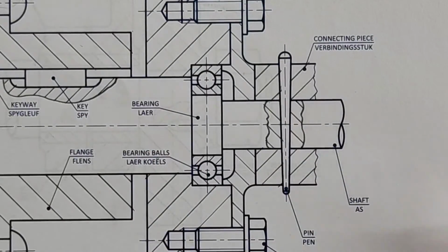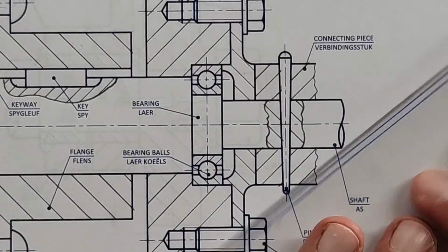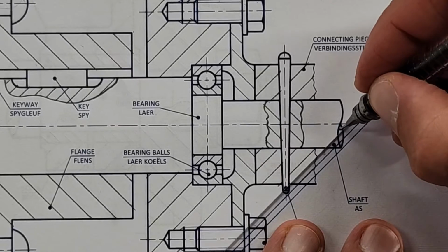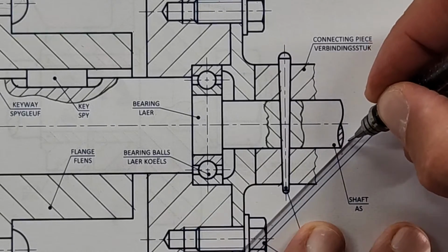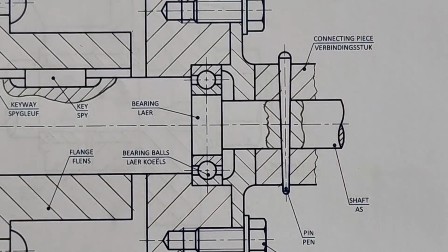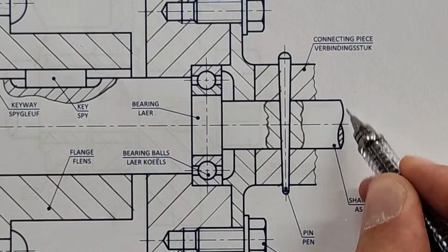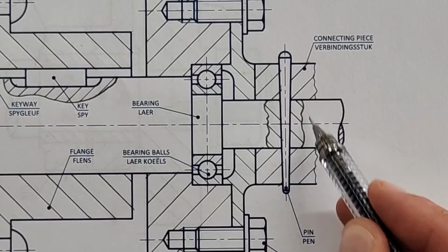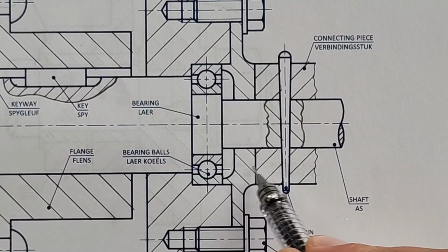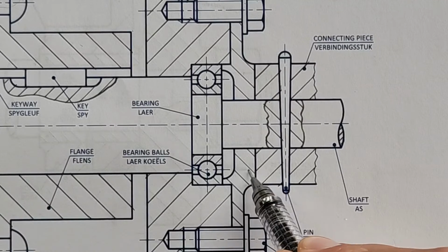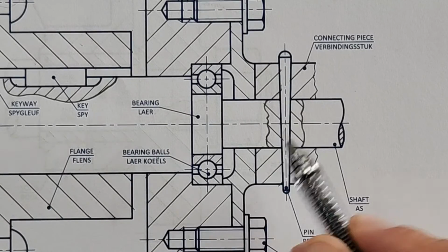Okay, so when you come to the final exam, they're just going to say, insert the correct hatching. There's not going to be a YouTube video to tell you how that looks. You'll have to go through every component. Make sure you don't miss the shafts. Make sure you don't miss any partial sections. Make sure that adjacent parts aren't competing with each other with regards to hatching.